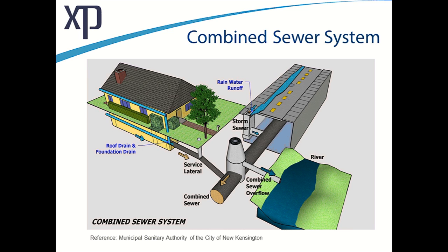What we're going to talk about today is combined sewer modeling. And it's so tied into sanitary sewer modeling that I wanted just to explain a little bit about how this works. So back when we first started working and designing and laying out our streets and homes and businesses, we put one sewer in the street, and we connected our service laterals, which picks up our sanitary sewage, and we also attached our storm sewer to that.